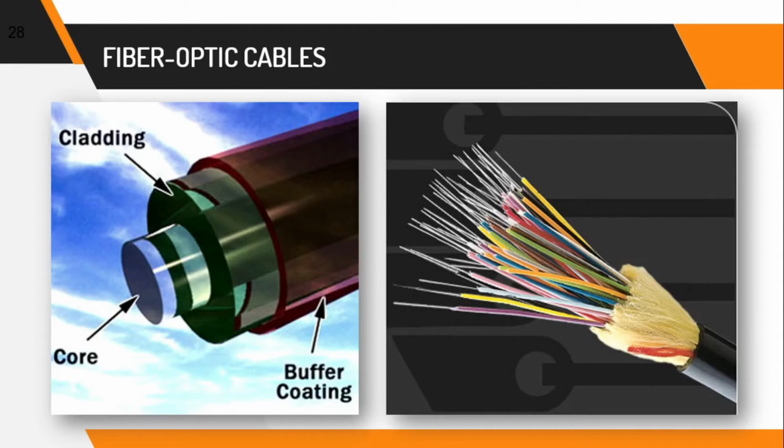Single-mode optical fiber networks often use wave division multiplexing techniques to increase the amount of data traffic that the strand can carry. WDM allows light at multiple different wavelengths to be combined, or what we call multiplexed, and later separated, or demultiplexed, effectively transmitting multiple communication streams through a single light pulse.